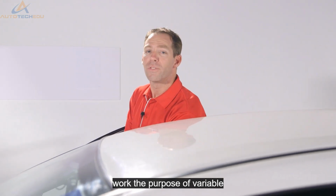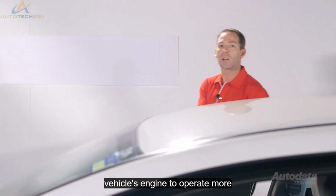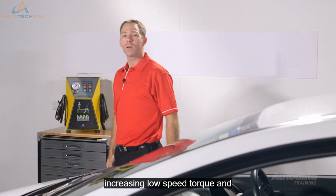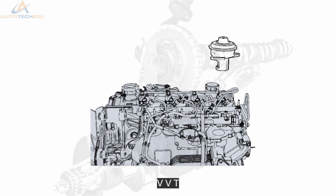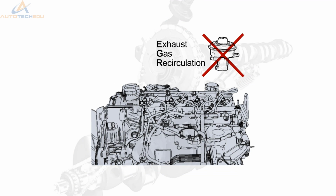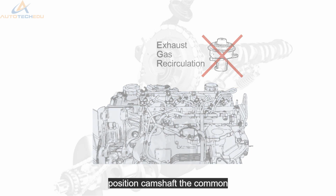The purpose of variable valve timing, or VVT, is to allow the vehicle's engine to operate more efficiently throughout its power range, increasing low-speed torque and high-speed performance while decreasing harmful emissions. On some engines, VVT has eliminated the need for exhaust gas recirculation valves. This is not possible in an engine with a fixed position camshaft.